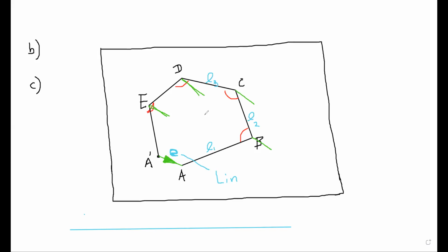Similarly, in this case, there are two types of measurements, right? The total error can be created as a combination of both, but the angle parts are already corrected. Angles are corrected, only lengths are remaining. Therefore, this error is due to the length. So we name it linear error or linear misclose.